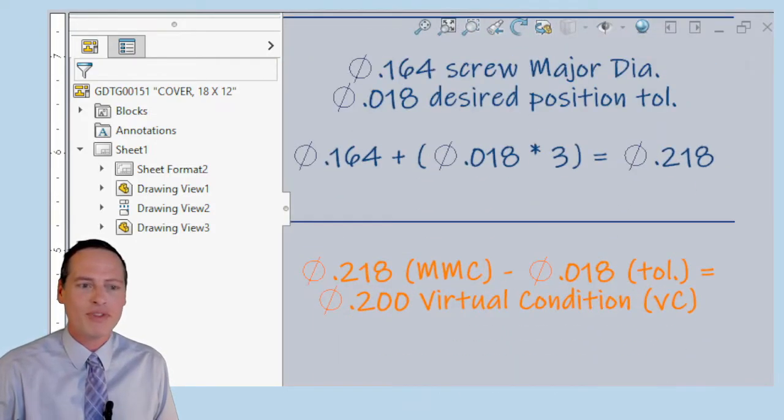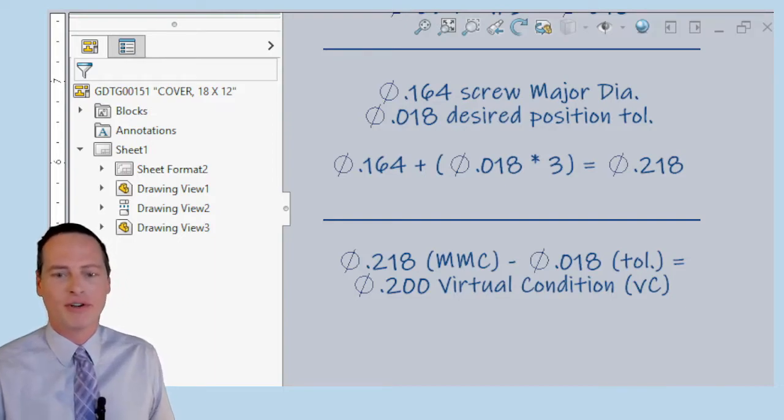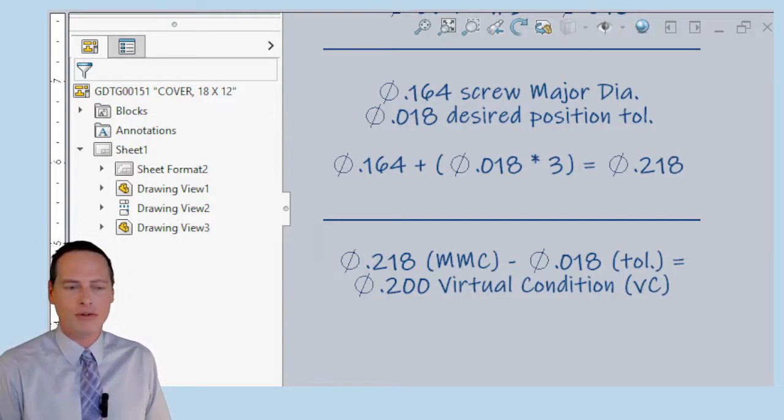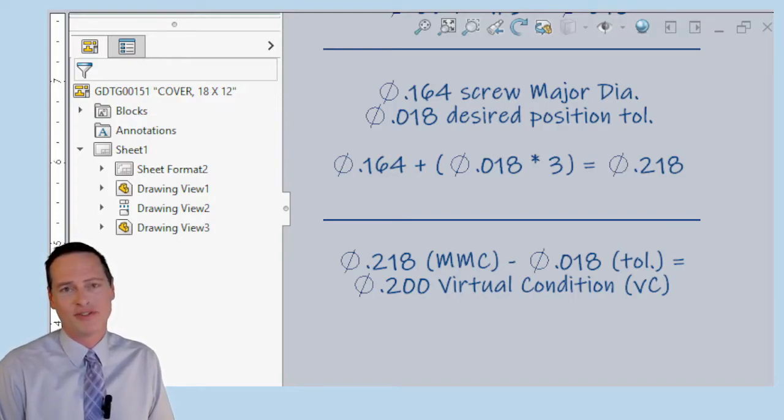And so that's it. The very first thing you can do to make it more likely that this part is going to fit is just to make those holes larger. And, like I did on the assembly, use some washers to cover up those big holes. No big deal. The washers are much bigger. They're like .360 or something. So think about that, okay?